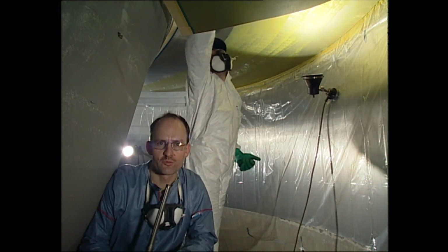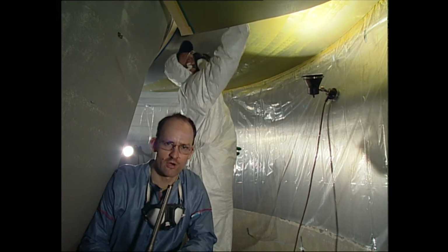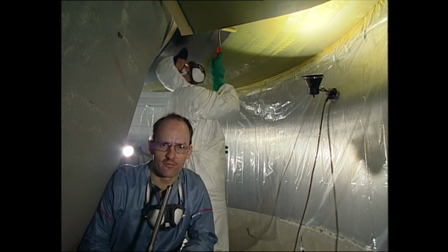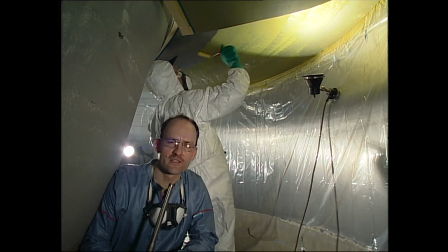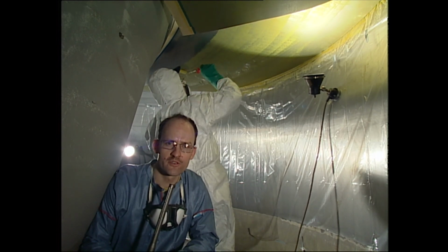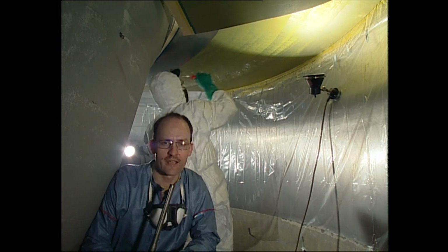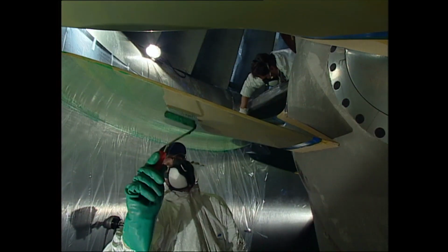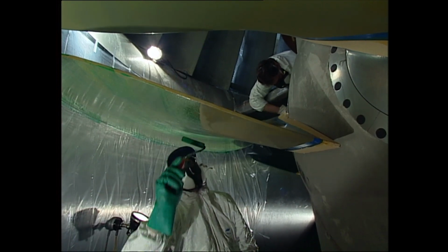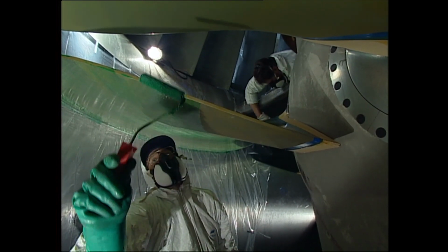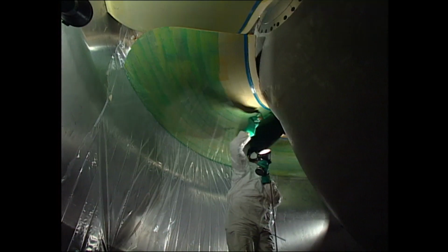Application can be done by spraying, by brushing, or even by troweling. In principle, therefore, it is a simple craftsman's process. However, every care has to be taken to ensure a proper surface preparation and a safe handling of the materials. The application of a bonding agent as a second layer ensures the bond of the top coat to the base material.